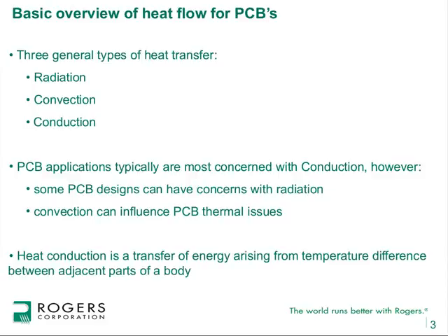So with that, let's go ahead and get started and talk about some heat flow. There are three different types of heat transfer: radiation, convection, and conduction. In printed circuit board applications regarding thermal management, conduction is typically the issue that we're most interested in, even though radiation and convection can be involved as well.